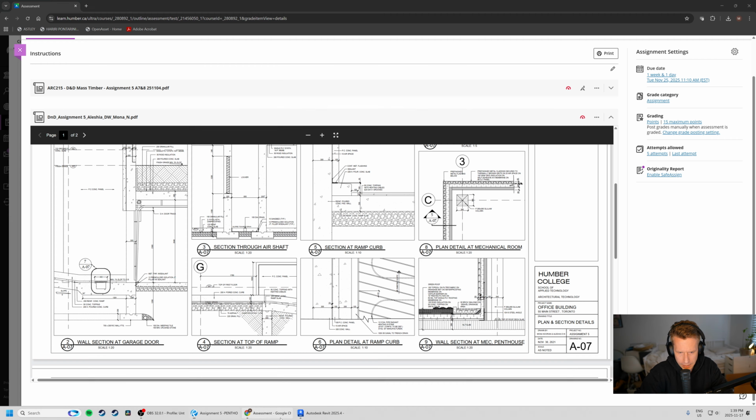You can update that number here, right? We can update it. Oh, come on, give it to me. I'm not sure why this isn't letting me. I should be able to. Anyways, if you can't do it there, if you click on the view, you can do it over here. If I change this back to 1, hit apply, ta-da, we're back here. So I will also be able to update it here. If I change this back to 45, you guessed it, it goes back to 45. So for now, we're going to keep it as 1. Interesting. Why can't I? Aha, there it is. So in order to change it in the sheet, you've got to click on the view itself, come over here, and then you can update it.